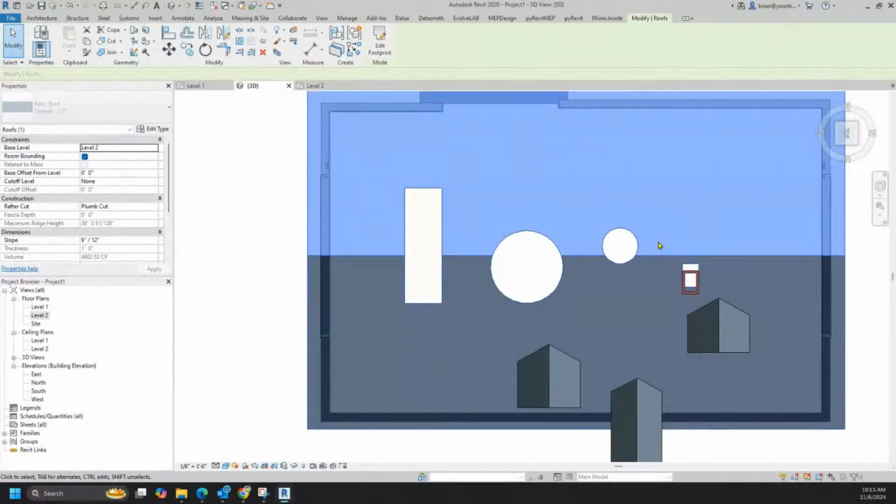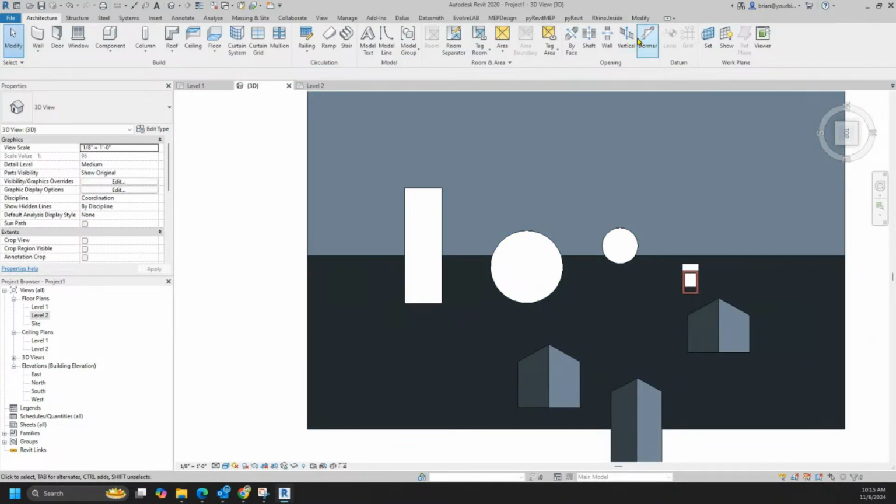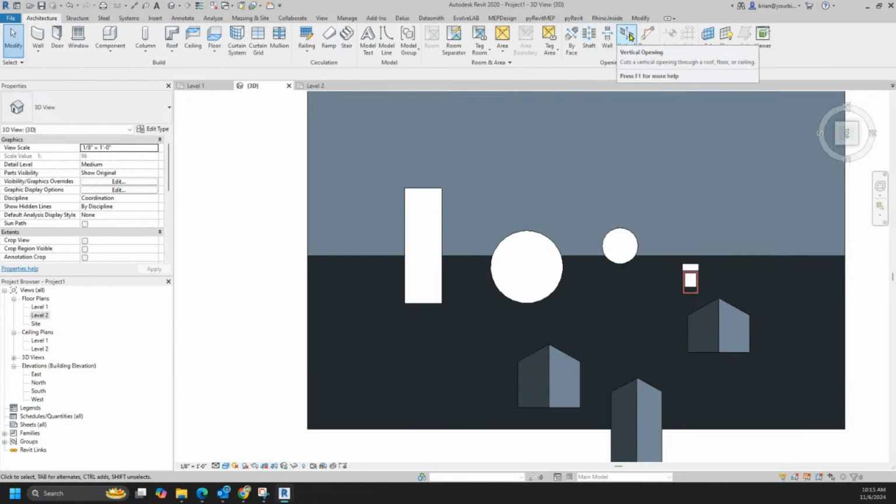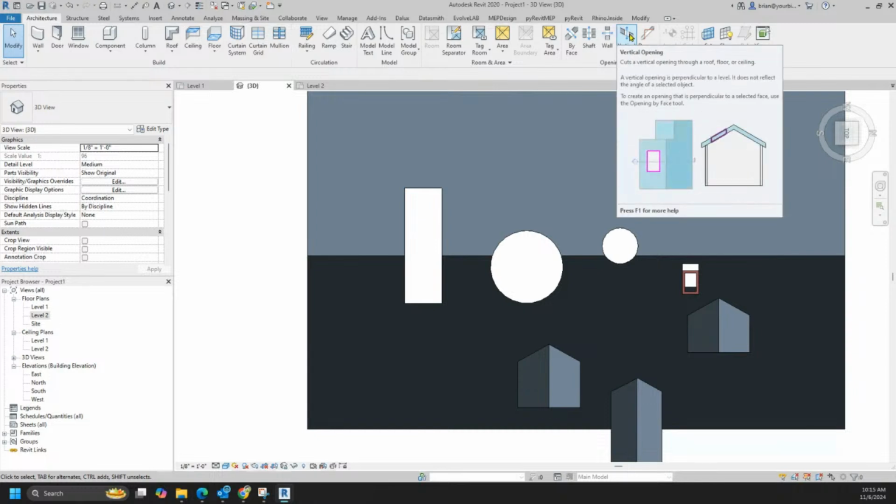You see how the chimney moves? The chimney hole is moving with the roof. That's because I did it inside the sketch. Okay. So if you wanted to keep that hole for the chimney, but maybe say move the skylight, you could use those two different ones. Absolutely. You could use the difference between. So you would use that vertical for the chimney, and then just slap the roof on top of the roof for maybe say a skylight.